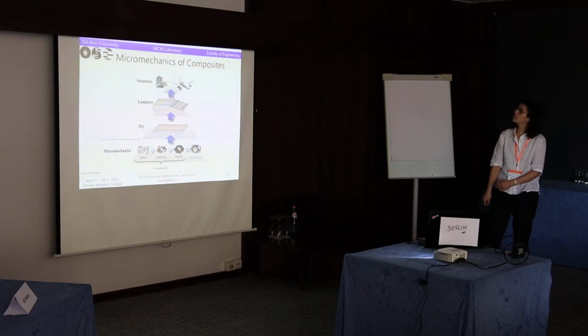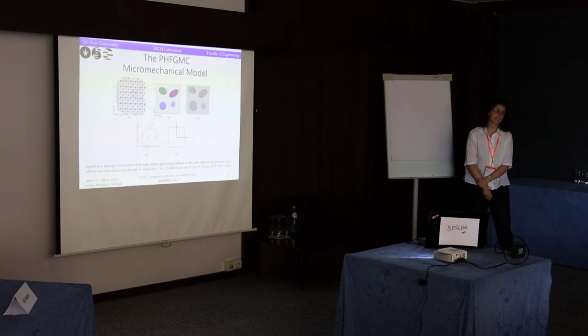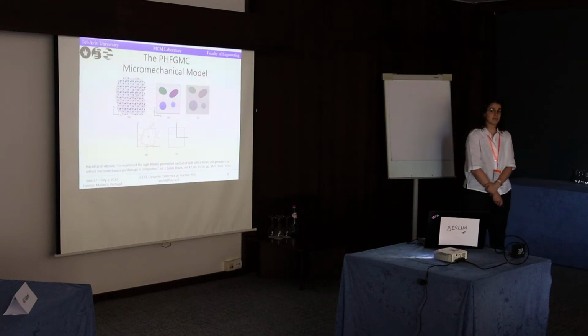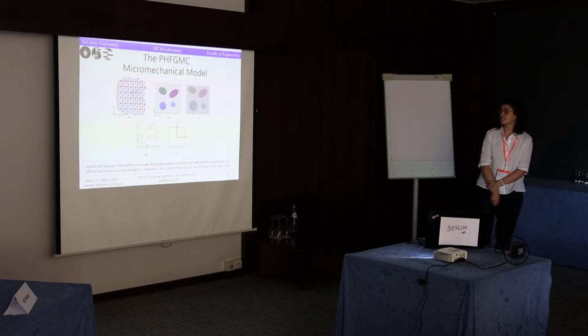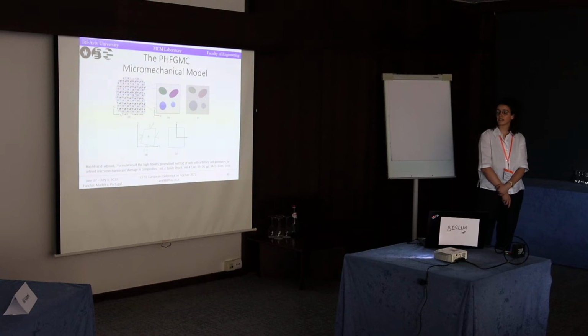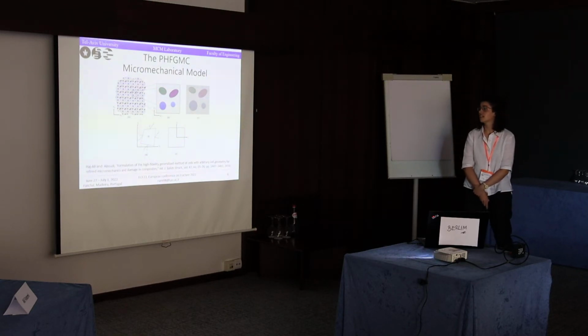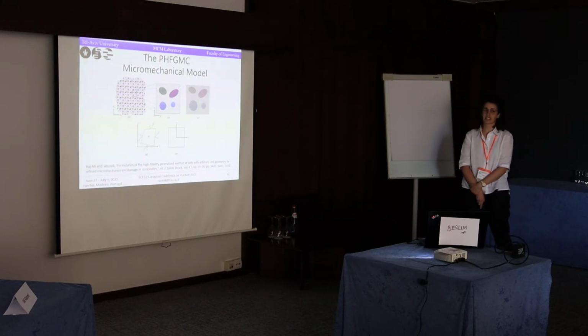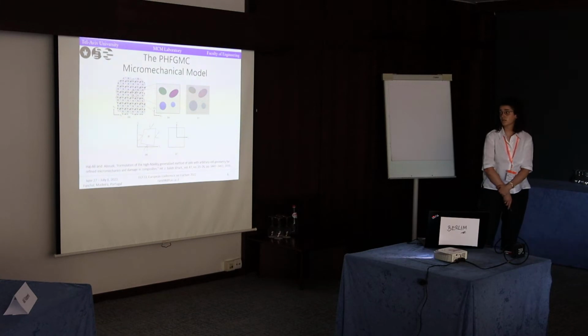And our micromechanical method is the PHF-GMC, the parametric high fidelity generalized method of cells. And in our case, you can see here the RUC constructed from the lamina in double periodic material or lamina. We can use a two-dimensional RUC, and it sometimes seems like finite element analysis, but it's actually not.